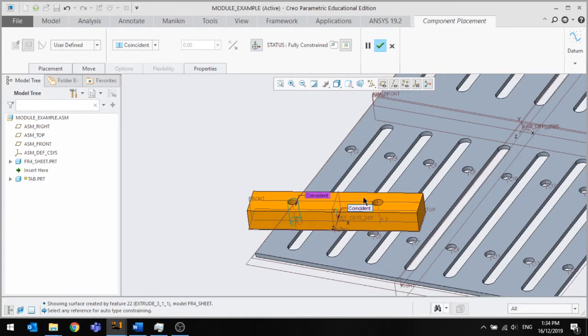And this is a common occurrence when you have something cylindrical matched with something else cylindrical and it's coincident, because it says, oh, I'm locked in place, but it's not actually. So it's common to trip over yourself doing something like this, because it says, I'm yellow, I am properly constrained, but you're not. So you might run into the issue where you've saved it, you've closed it, you've gone and, I don't know, built something in the workshop, come back, and then your model's broken, and it's because you haven't actually constrained this thing properly.